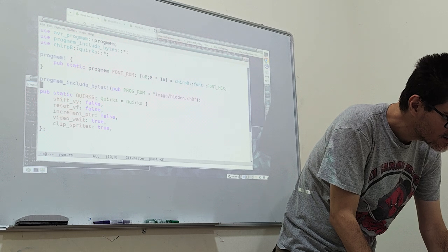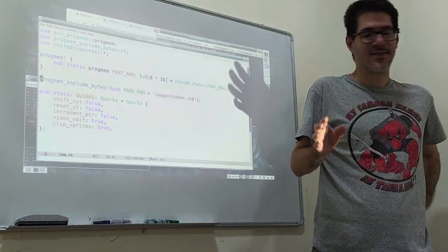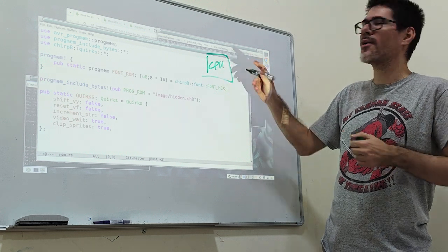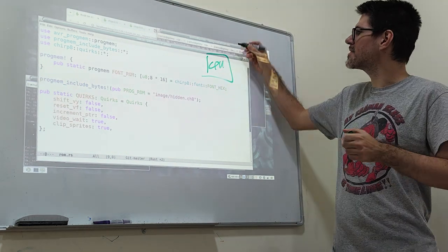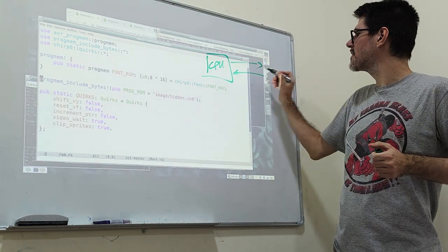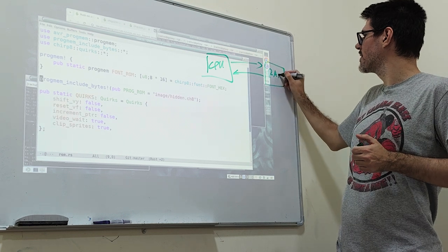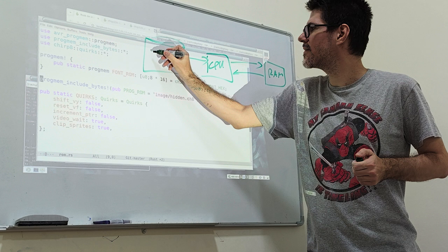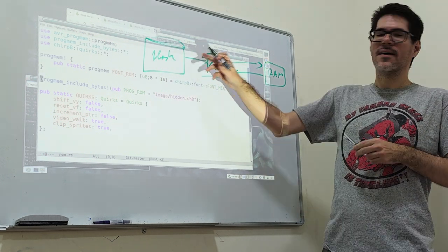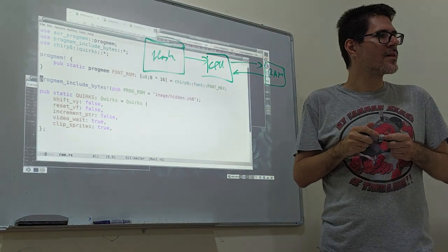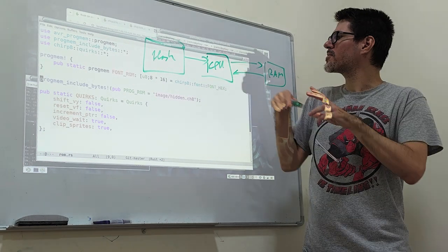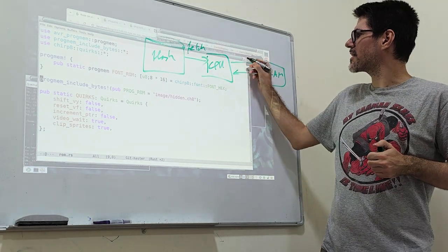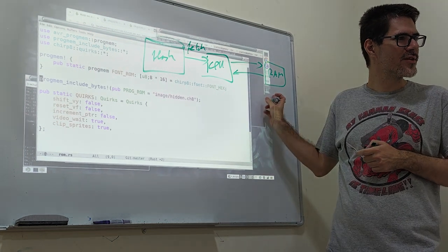Sorry, what is the memory model for that chip? It's a Harvard architecture. So all of this is obviously on one chip, but then your CPU has the main RAM, and it has flash. So it doesn't act like a hard drive in a Unix system, I guess. No, no. So the CPU can only fetch from here. Like you can read and write, but you can't execute from this side.